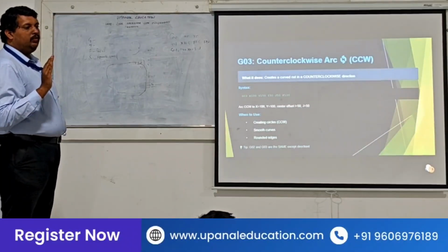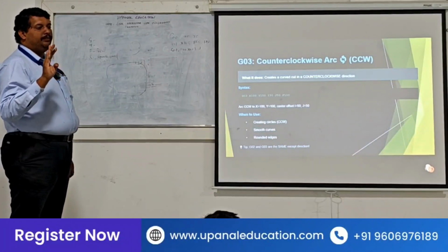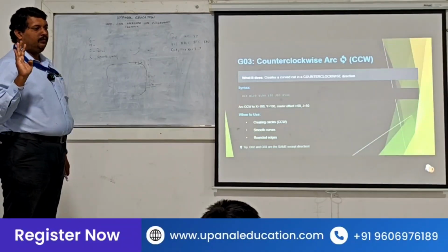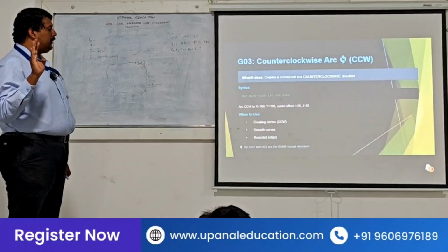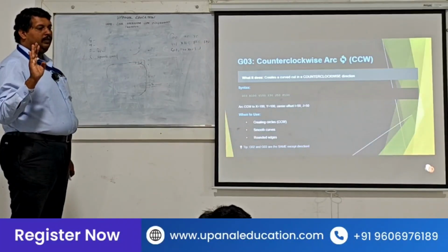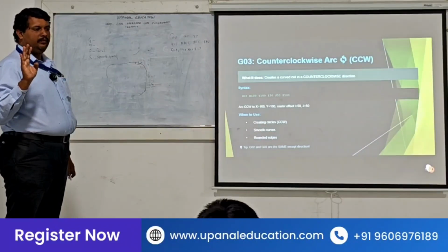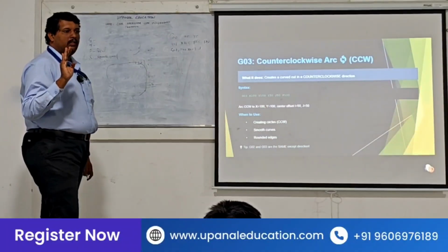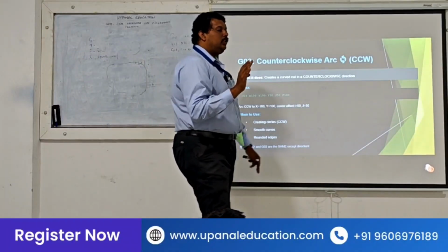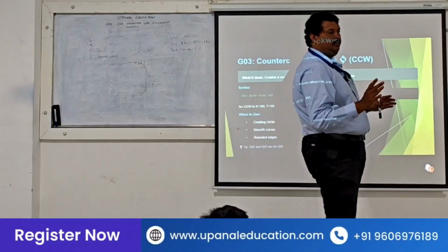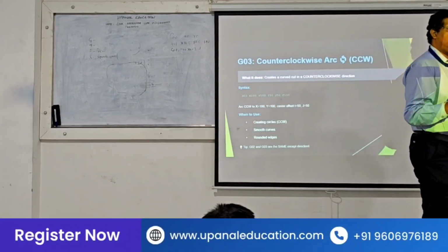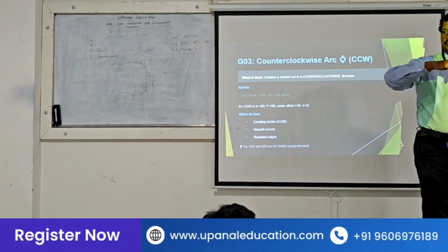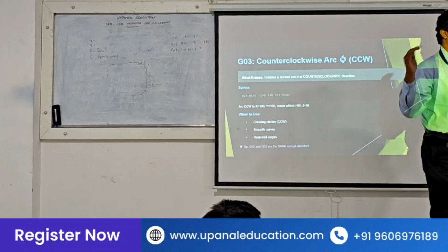Understood? Any doubt about this now? G00, G01, G02, G03. Any doubt about these four things? You will always remember this? G02 to G03, what is the difference? Everything is the same. The only thing is, it goes from left to right or right to left.